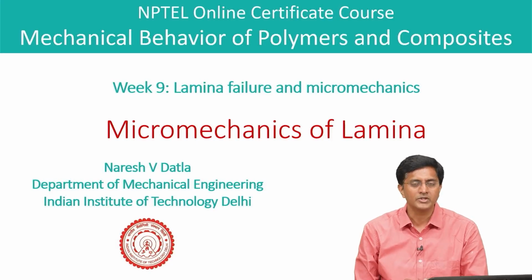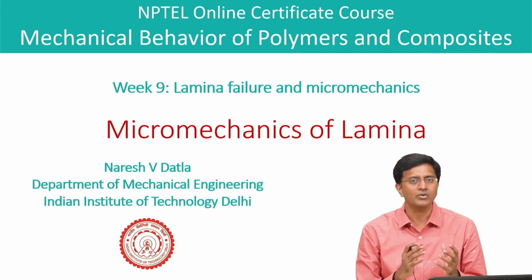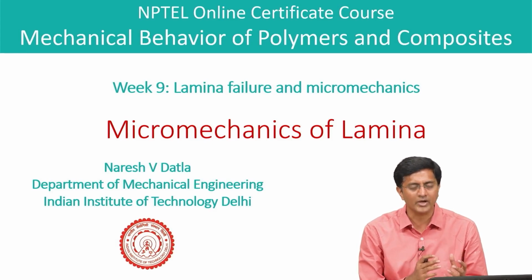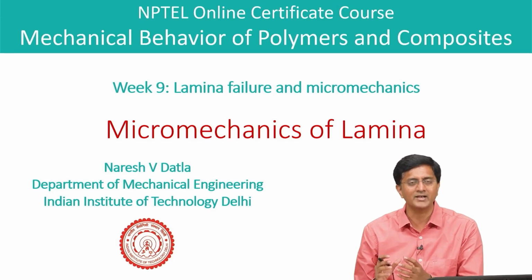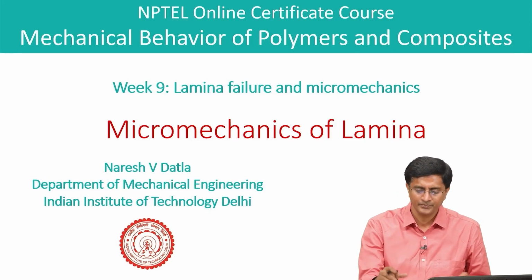Hello all. From this video we'll start discussing the micromechanics of lamina. As we already mentioned, micromechanics is when we look into the details of the lamina, which is composed of the fiber and the matrix material. So the idea here is, if we know the properties of the fibers and the properties of the matrix material, can we use this data to predict the properties of the lamina?